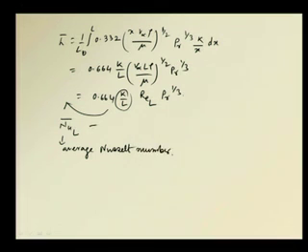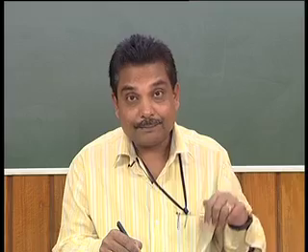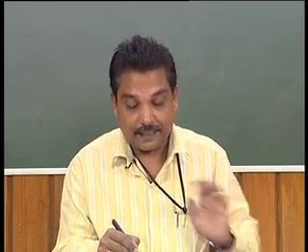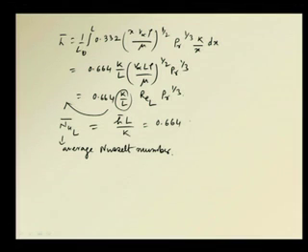And this is becoming equal to h bar L by k. So, Hx is replaced by h bar, x is replaced by L, k remains as k. So, this is equal to 0.664 into Reynolds to the power half and Prandtl to the power 1/3,